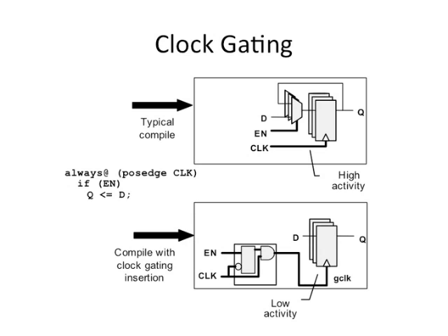The gated clock has a skew compared to a non-gated clock. So you have to account for that explicitly. It's not hard to account. You just have to make sure that everywhere you insert this kind of gate, all the clocks get delayed by the same amount. So it's not such a difficult problem, but it's just something which has to be paid attention to.